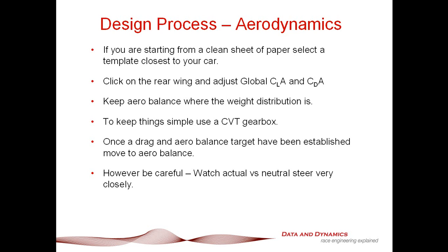If you're starting from a clean sheet of paper, I would strongly suggest you pick a template that most closely resembles your car. Let me give you some rough rules of thumb. If you're designing something like an F3 car, use one of the ChassisSim F3 templates.